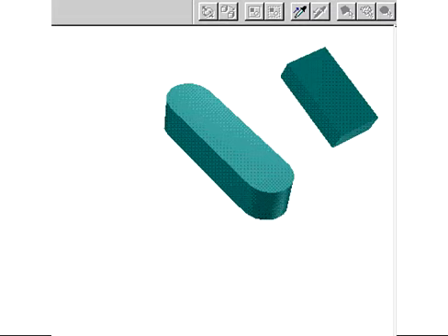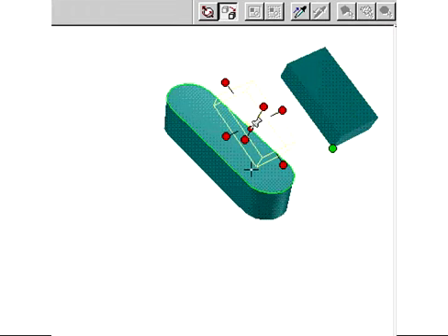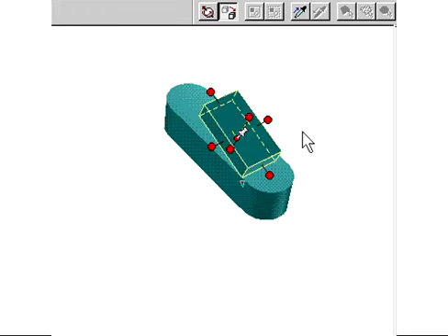Use the Move From To tool to line up one shape to 3 intersection points with another shape. Select the shape, then select the Move From To tool. Click and drag a point on the shape and drop it on the target point of the second shape. This action joins the two shapes at a single point, constraining the motion by this point.